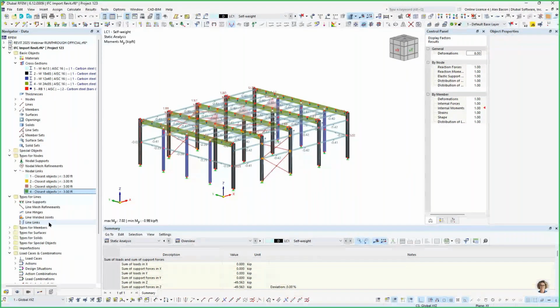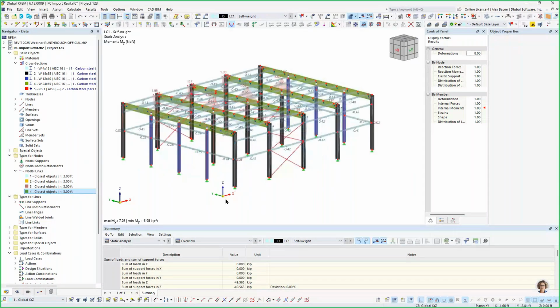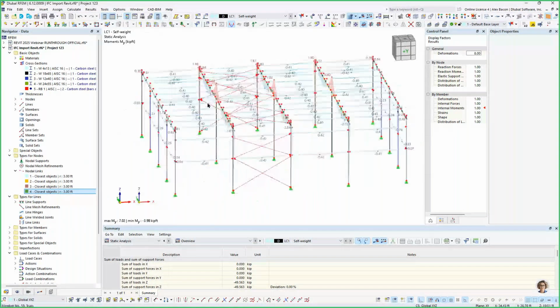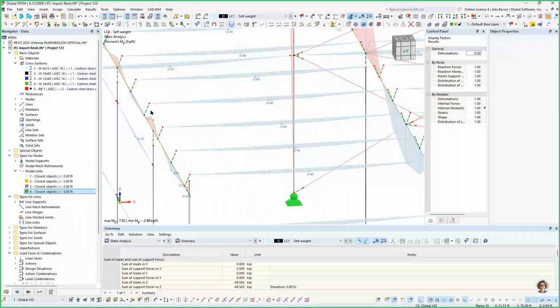And so this workflow can be an alternative to the direct link. It's great since CAD programs can import and export IFC files. You can also leave the beams basically where they are with these eccentricities, because these eccentricities would have had to be added in anyway.